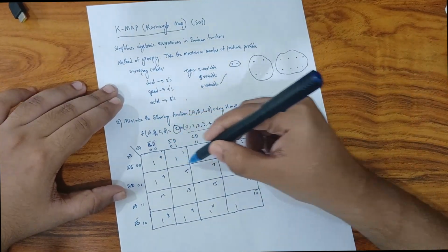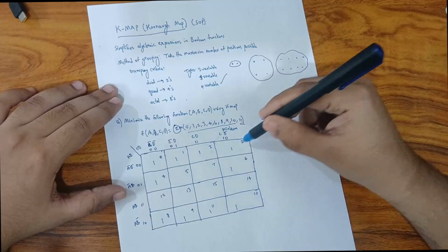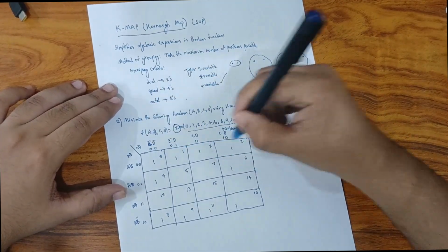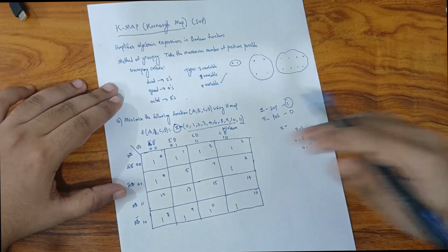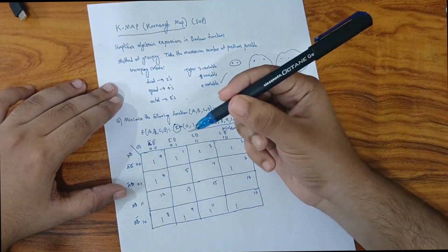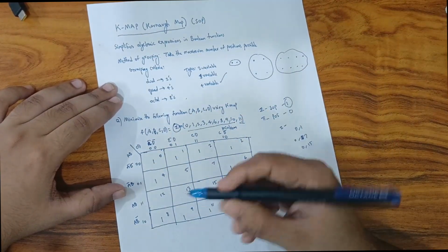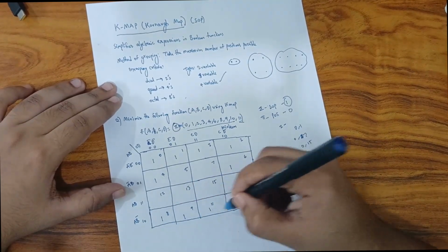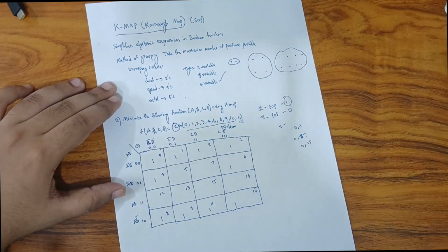We are seeing a lot of common elements in this adjacent. They are adjacent to one another. You can see 1 1 1 1. They are all adjacent to each other, so we can put them under one group, I guess. But no, look down, there's another set of ones, 1 1 1 1. So you basically can't keep a quad.